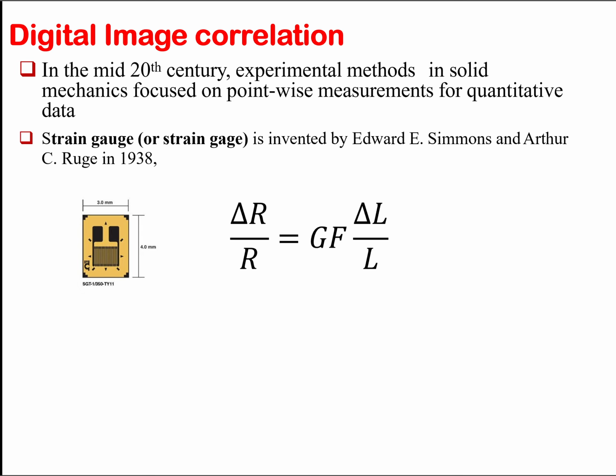This is a very useful sensor that we can use to measure the strain. But the problem with it is it only gives us a strain at a specific point, which is again helpful in a lot of cases, but for a plate buckling analysis, for example, not that helpful. We need to have a bigger understanding of the deflection that is happening throughout our field.